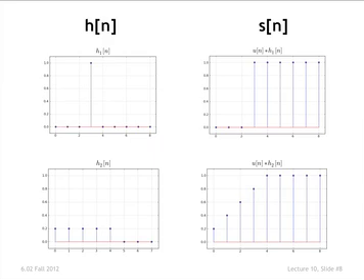So when this comes back down to 0, what the step response has settled to is sort of the integral of this. It's the area under this. But we're talking about discrete time functions, not continuous time functions, right? So the value that it's settled to here is the area under this. The duration of a unit sample response gives you some feel for how long a transient lasts. So if you've got a channel and you hit it with an input, you know that the transient will last about as long as the unit sample response lasts. So the transient in the step response shows that clearly.